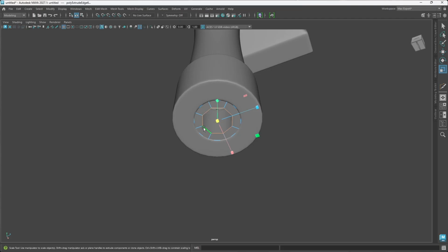If we decide to connect this to this, so we're going to have 1, 2, 3, and 4. So let's right click and go to fill hole. Now we'll fill the hole, hit M, select the multi-chord tool. We can move this to this. That is 1, 2, 3, 4. It is not going to work.